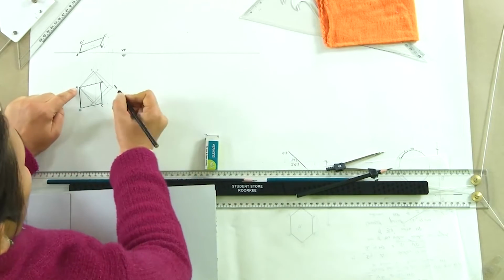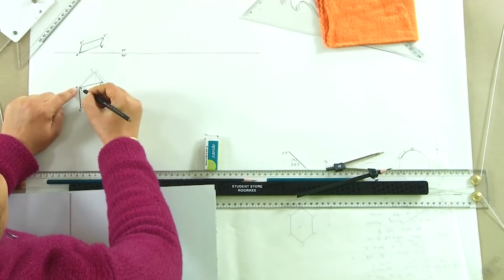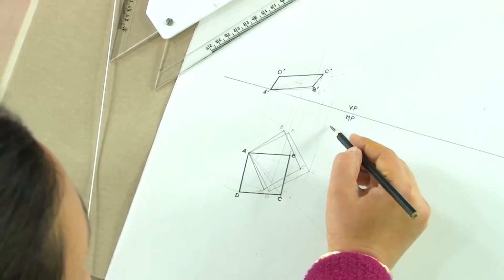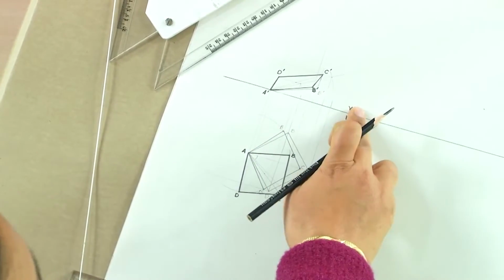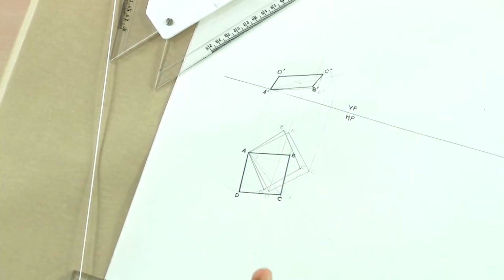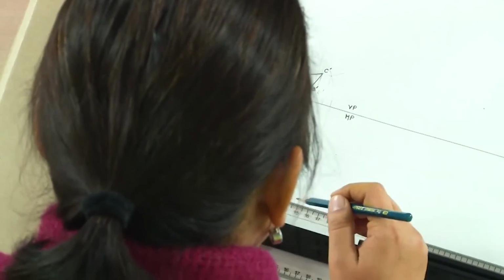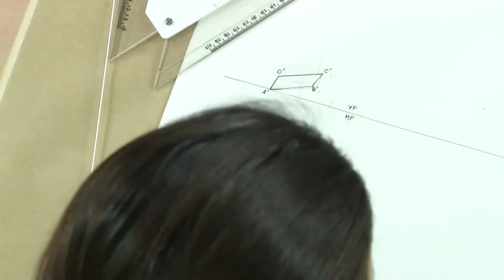This entire shape which we had got as the second rhombus, ABCD here, that would be rotated in such a manner that a true angle which BD makes with VP is reflected. It is seen here. Let us quickly see that to give a slight twist to the same problem. So we start again with the same square, which was a square of 4 centimeter side.